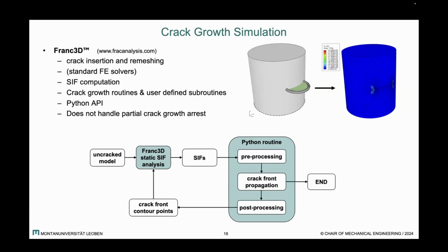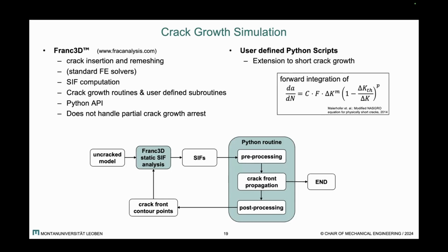But what it does not handle is short crack growth, so a partial arrest of the crack front. And that's why I'm only utilizing the static SIF analysis of each crack point and implemented the short crack growth simulation in some custom Python scripts. I won't talk anymore about the simulation intricacies because of time constraints.